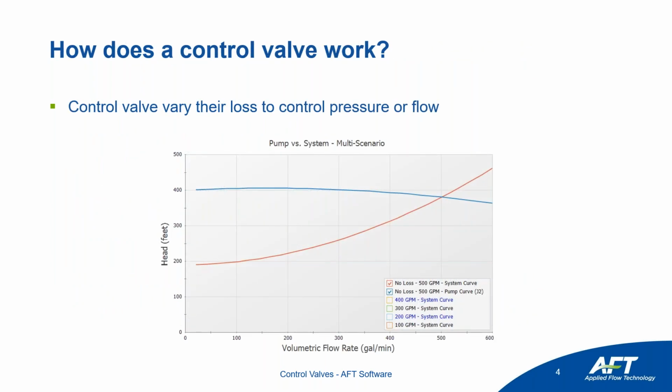So we understand why we might need a control valve. Let's take a second to understand conceptually, how does a control valve work? The control valve, again, is a variable element. You can imagine a valve like on your sink. That'd probably be the valve that we interact with the most in a day-to-day sense, where we can have the valve fully open. That allows our maximum flow. And if we wanted to reduce that flow, we can close our valve gradually.